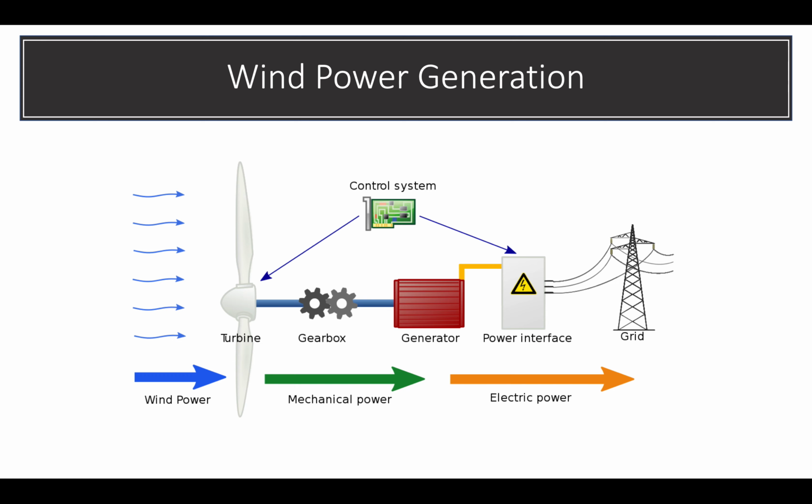What wind turbines do is essentially convert kinetic energy in wind into mechanical power and then into electrical power. The majority of wind turbines consist of 3 blades which are mounted to a tower made from tubular steel. There are less common varieties that have 2 blades, but we're not really going to focus on that in the class. So at 100 feet or more above the ground, the tower allows the turbine to take advantage of faster wind speeds, which are just found at higher altitudes.